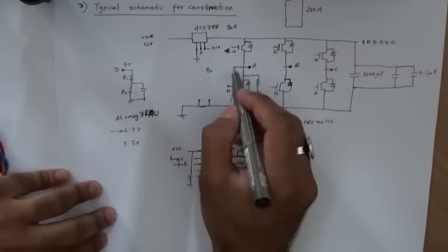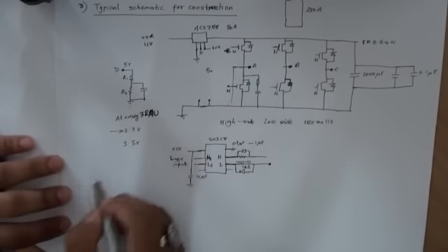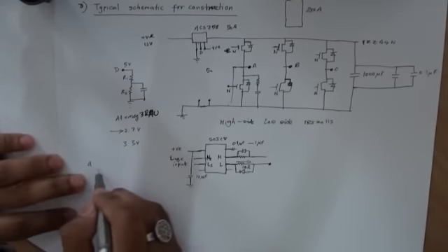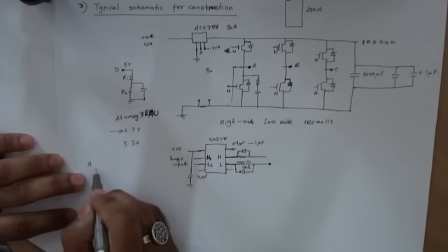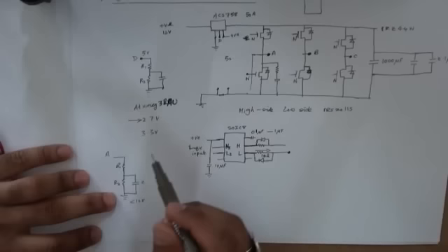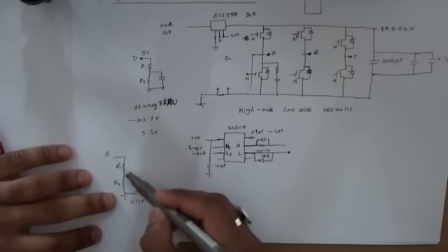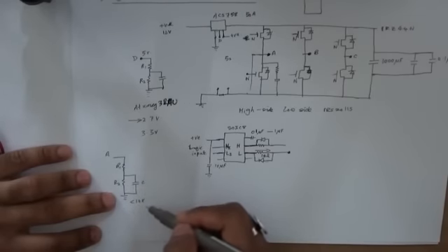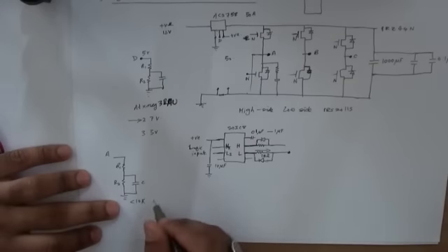So you want to create a voltage divider network for back EMF reading. So if we look at just the phase A itself, you will have a resistor off to the ground and a capacitor filter. A few words of advice: you want to have these resistors less than 10k, and that'll give you noise improvement.